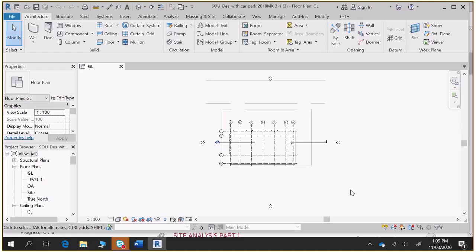Isn't it about old legislation and old title styles? Well, what it's about is that so many things used to be allowed. There was quite a bit more open slather previously. You didn't have to have fire separation walls between sole occupancy units. But whenever you create separate title for something, you need to get planning approval and building rules consent.